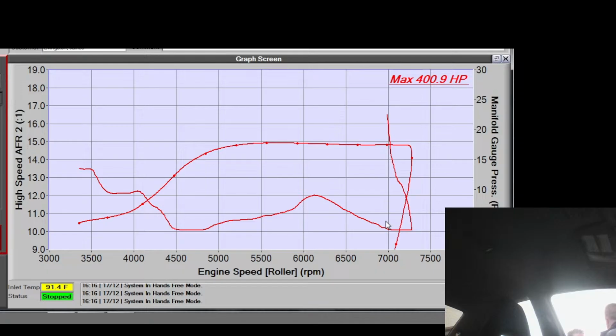No. This thing will not fuel. It just keeps doing that. That's the dampers causing a bunch of problems. This lean spike and this rich spike. You pull those dampers out, it's gonna go. Really? Yeah, it's messed up. What are the dampers? They're maxing out their throw because of the boost pressure, and then they go at certain times, based on the pulse in the rail, and so they create an uneven fuel pressure in the rail.